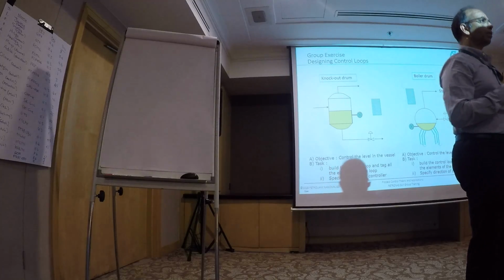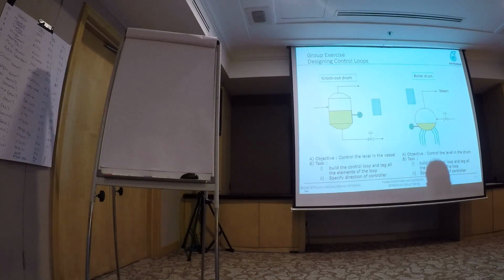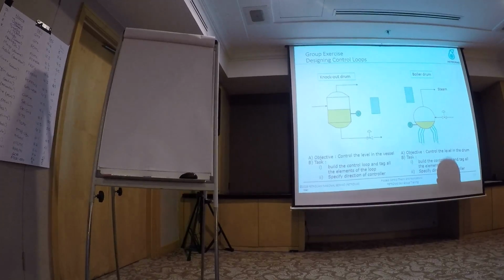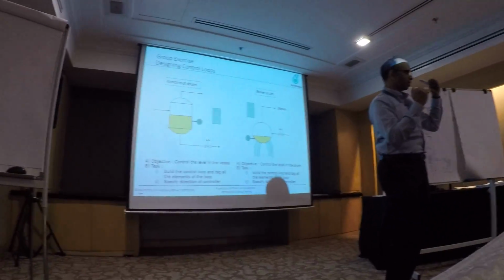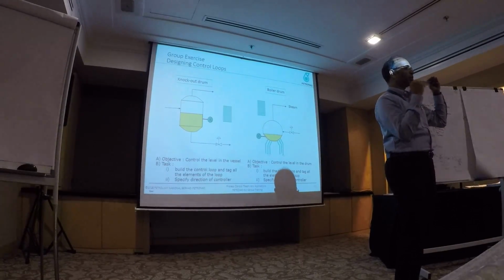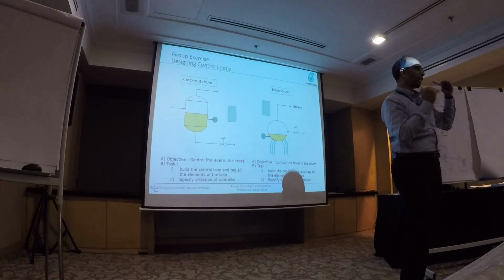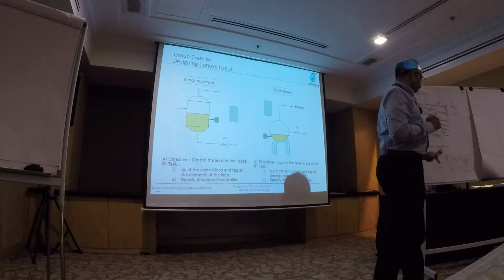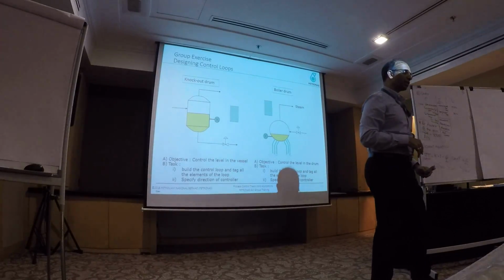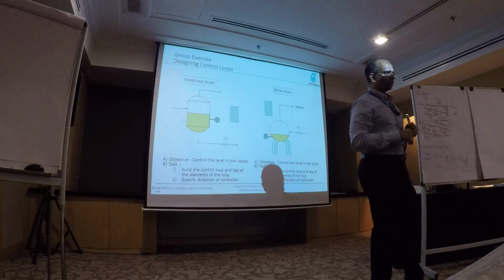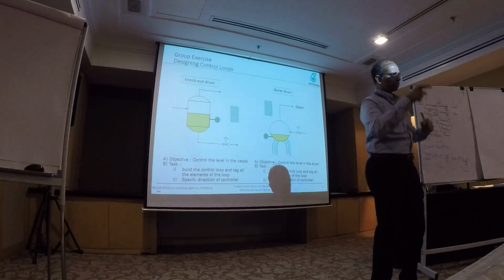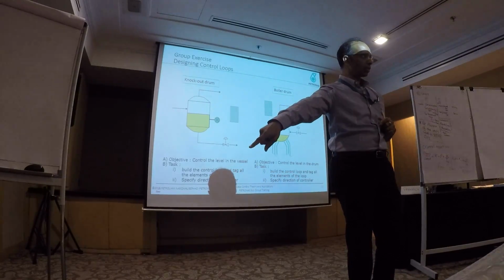Now think about it. Let's say you have something running at 50%, at the setpoint. Error 0. Level controller, and the level drops. 50 drops to 40. Impossible, but let's just say it happens. 50 drops to 40. What do I get? Instantaneously, I get an error of 10%. What does this block do? Let's say it's pure proportional, gain of 1. Error 10%. This calculates an output change of 10%.